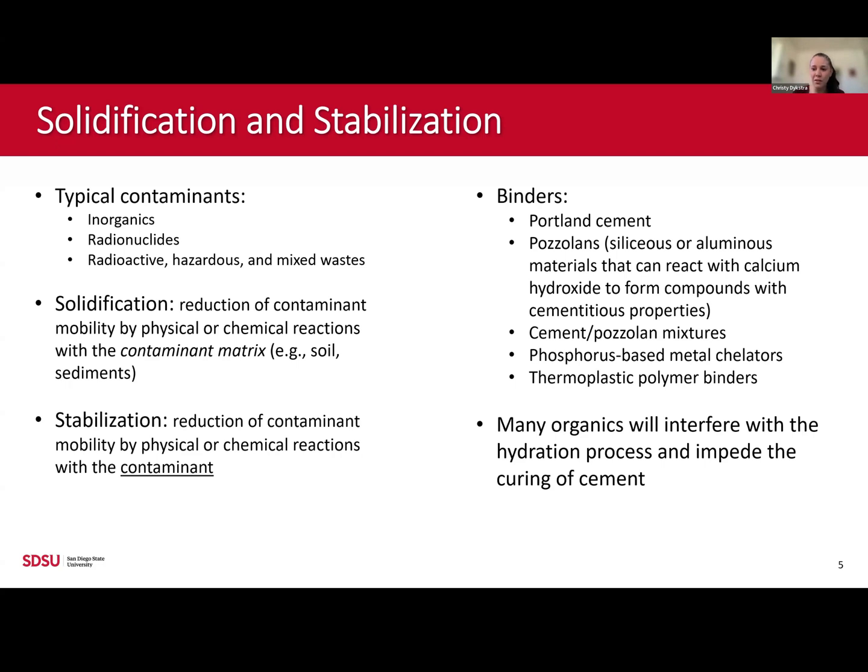But in general, chelators can also grab on and bind different contaminants. They might be able to bind onto those contaminants and also bind something else. And they might just make it so that those contaminants are no longer reactive with other things because they're so tightly bound to that chelator. So that would be an example of stabilization as opposed to solidification, which would be more like pouring in, let's say, the Portland cement or the binders or something like that, that's going to react with the soil matrix around it.